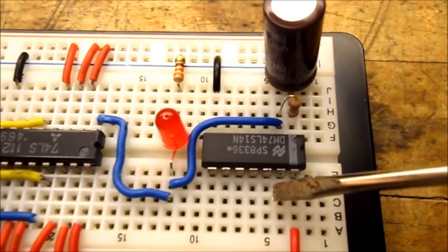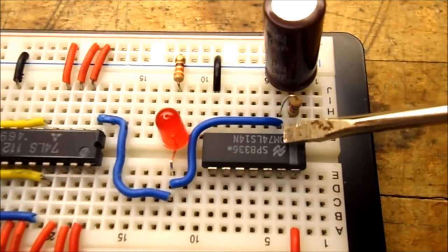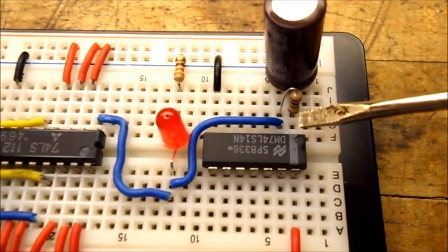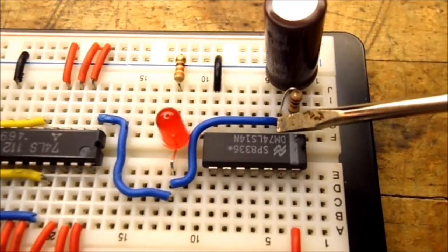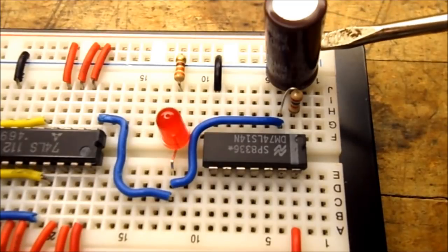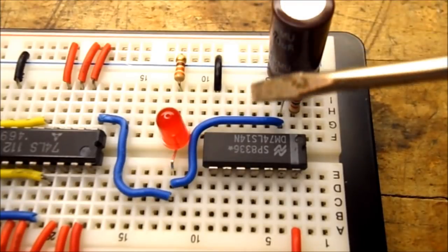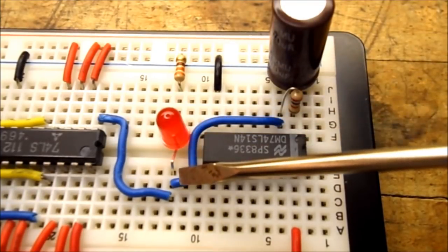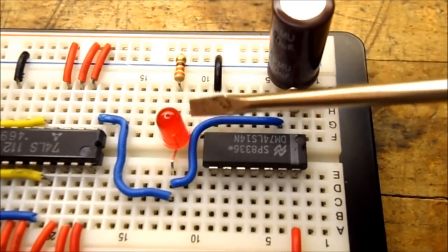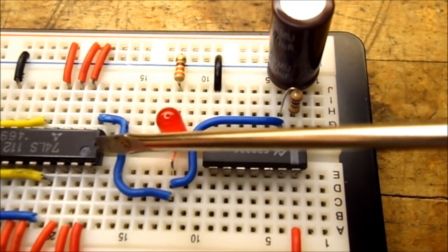So looking down from the top here, you can see this is my 74LS14, and I'm showing it to you at this angle so that you can see the little resistor here. That's my 2K ohm resistor going between pin 1 and pin 2, and my capacitor goes between pin 1 and ground. And remember, it's a polarized capacitor, so get that in the right way around. The output is going to come to my LED that goes through a 330 ohm resistor to ground. That output is also going to feed my JK flip-flop.